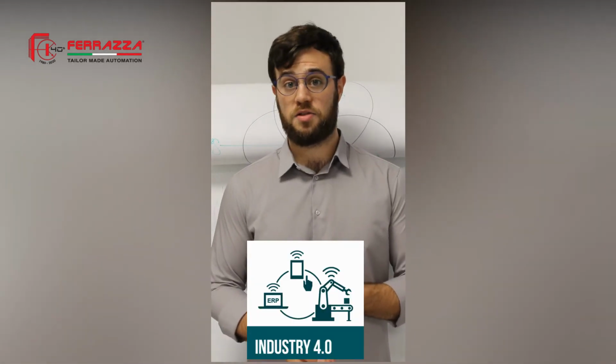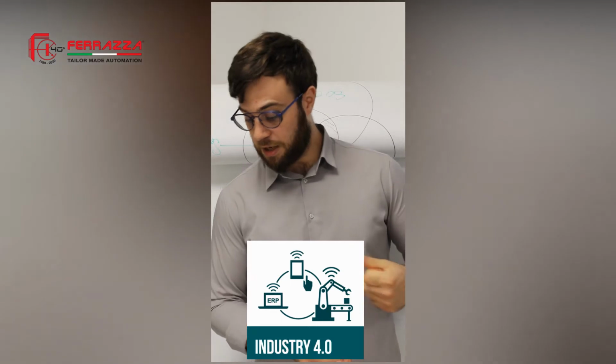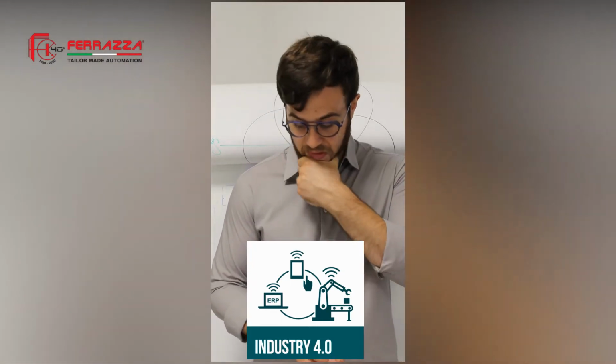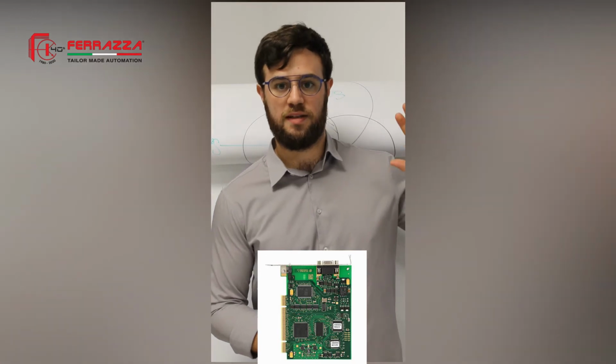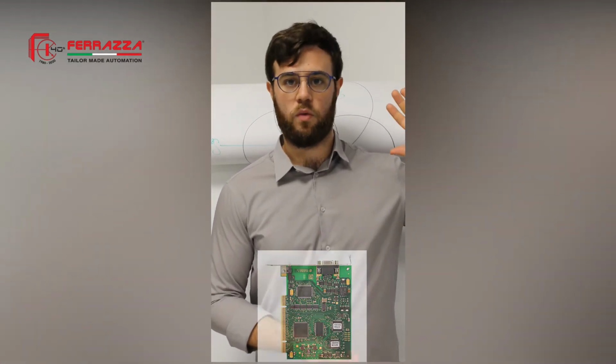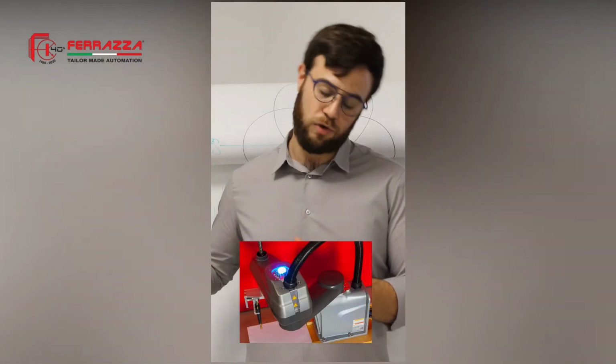But depending on where you're going to install it, you can have different items and equipment with different boards and accessories. For example, if I have to install a PLC in an Industry 4.0 system, I'm going to need a communication board so that the PLC can transmit data online and work with the SCADA, with the management software, etc.